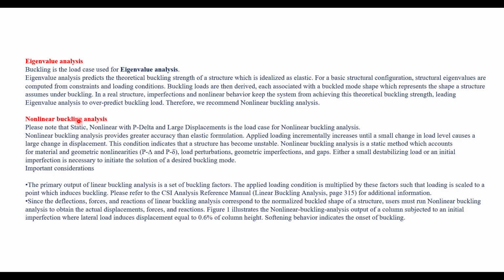So we always prefer to do the non-linear buckling analysis if you see the component is trying to fail in buckling in the static analysis. Even if it is not failing, we always recommend you consider non-linear buckling to validate your components, if your component is prone to buckling. That is important.